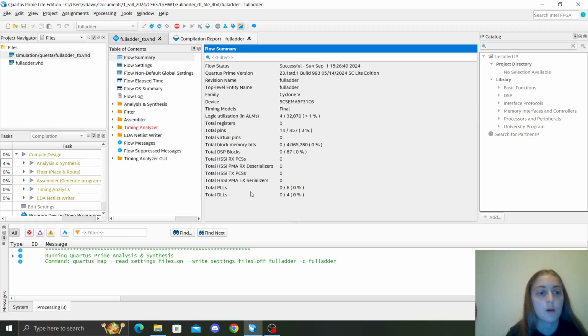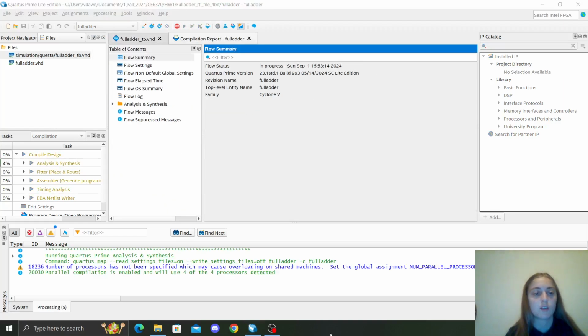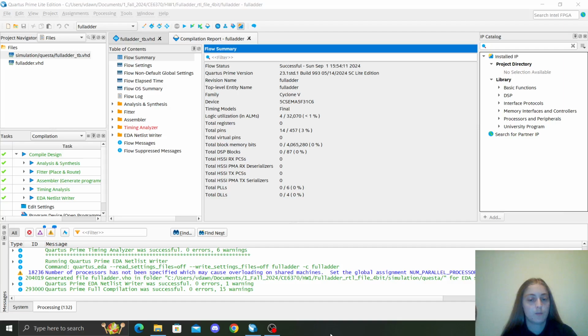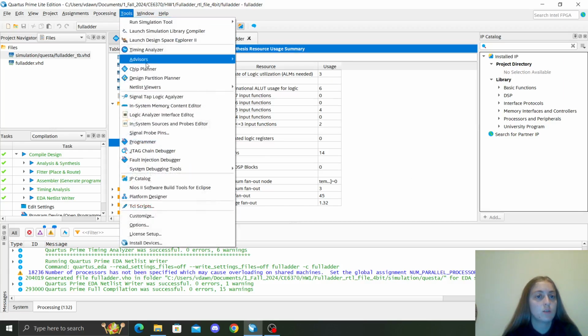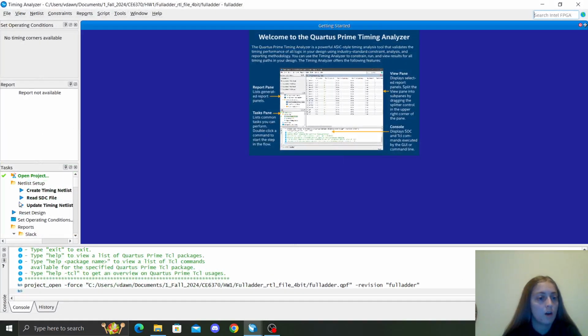So we're going to start the compilation process, and once that finishes, then I will be back. Alright, and the compilation was successful, 0 errors. And so going to analysis and synthesis, resource usage summary, 3 ALMs, 6 LUTs, 0 flip-flops, 14 IO pins, 0 DSP blocks. So that looks correct. And then next, tools, timing analyzer, and scrolling down to report path.